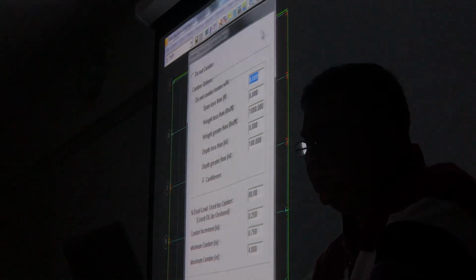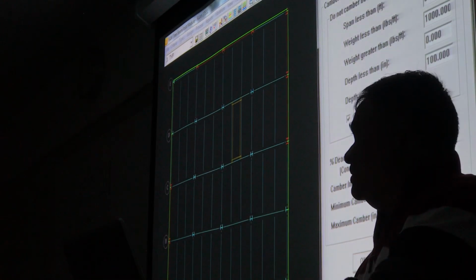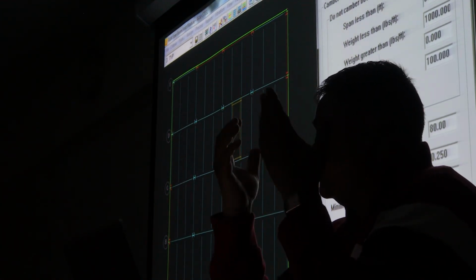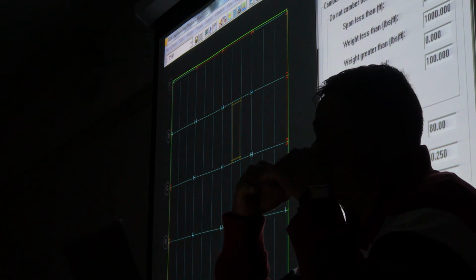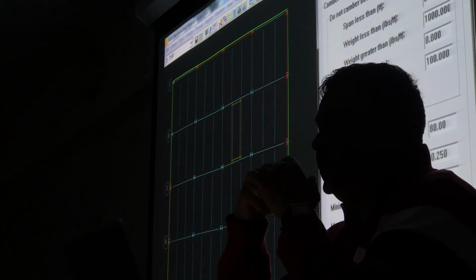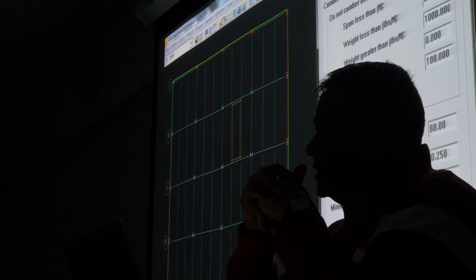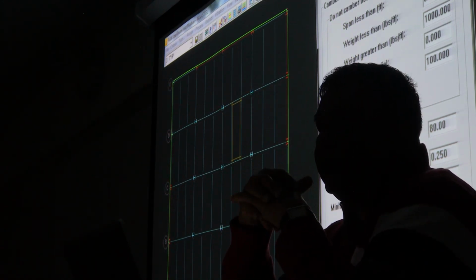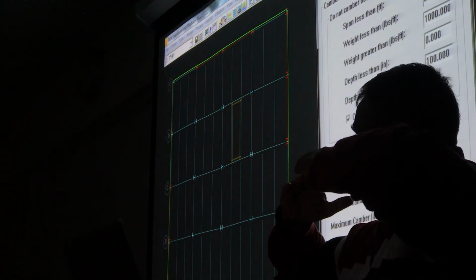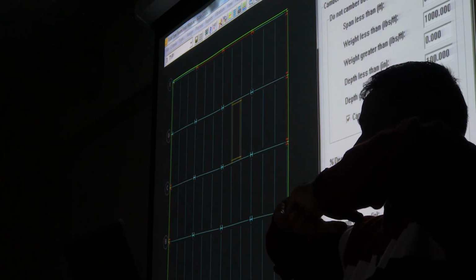Camber. Do you know what a camber is? Camber means, when it is a steel beam, even for self-weight, it's going to deflect. It's very elastic, right? So what we do is, if we expect the beam to deflect when the loads are applied, we calculate how much deflection it will be, and 80% of that we specify as camber. Instead of making it flat, if it is flat, then due to the load it will deflect like that.